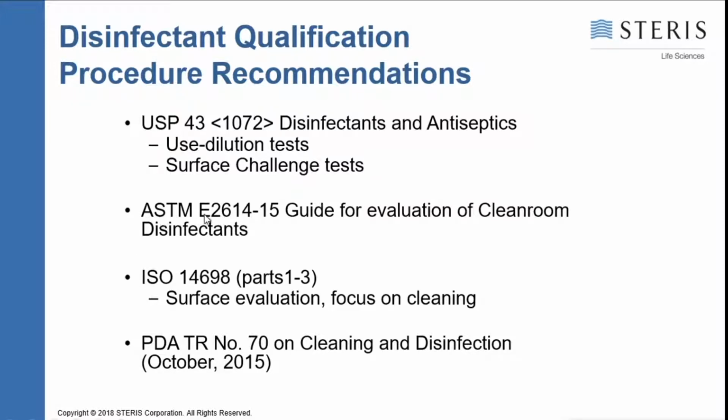Then there's also an ASTM guide out there that will give you guidance as far as how to validate the disinfectants in the clean room. Then there's the ISO 14698, parts 1 through 3, which really talk about only a surface evaluation. There's PDA Technical Report number 70, which focuses on cleaning and disinfection, but it has about 4 pages dedicated to disinfectant validation.